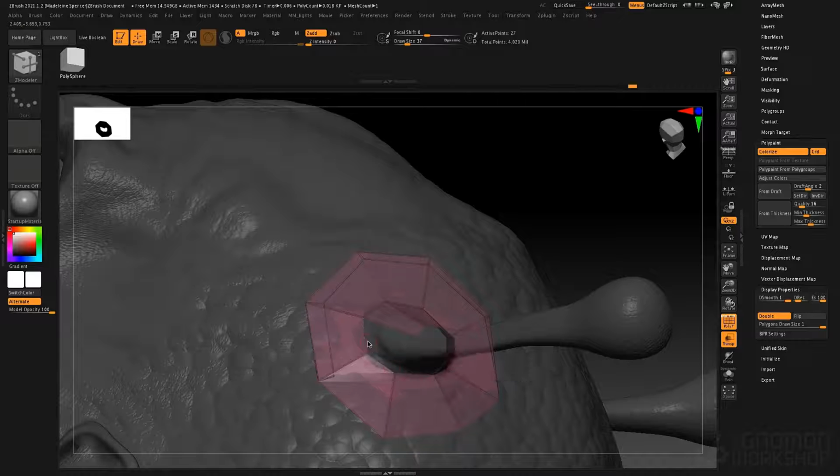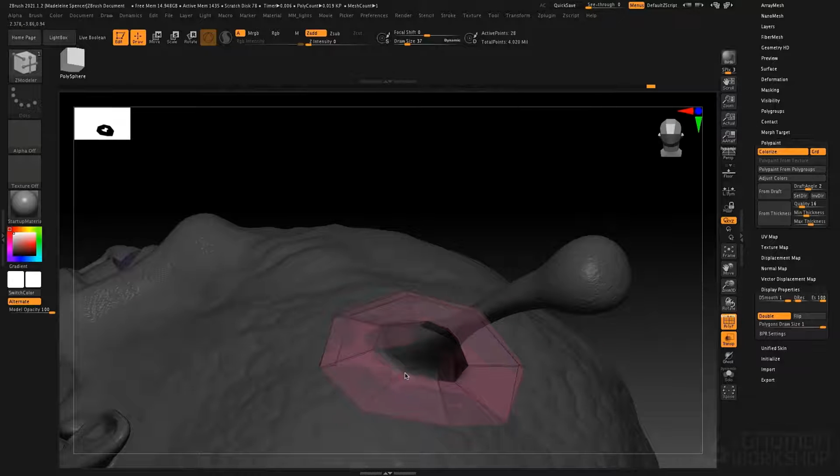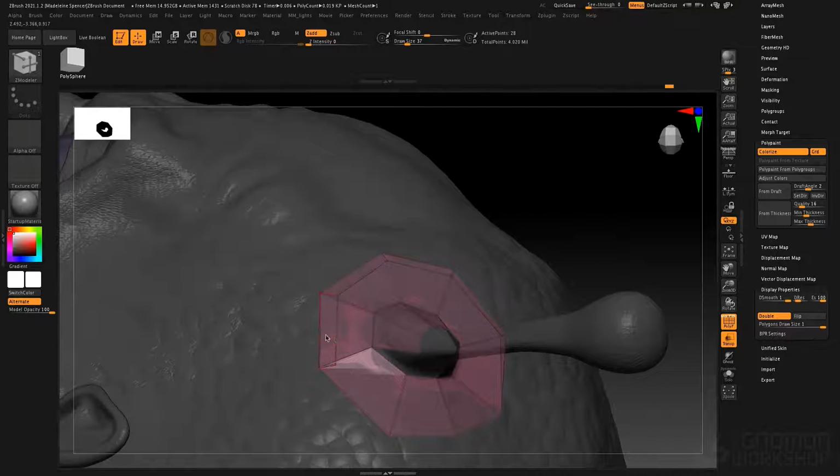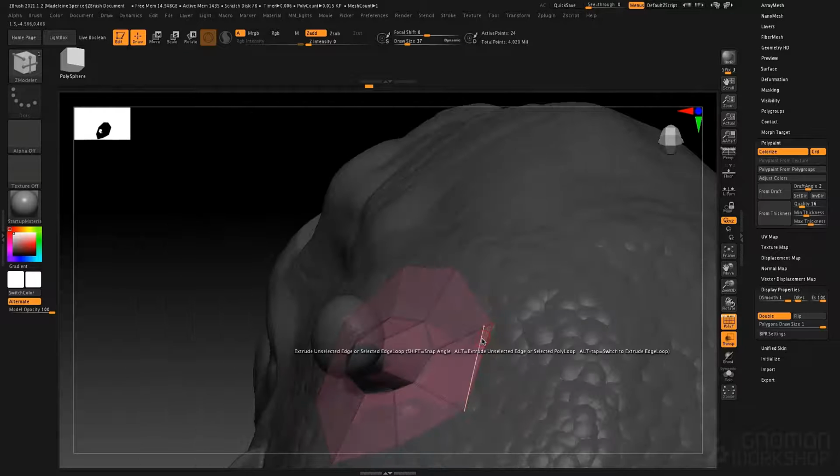And then we'll go back to our edge, bring this edge up to here, move this point, and let's move this point. So as we're adjusting these things, we can start to shift these faces around. Looks like we've got a little extra bit of geo right there. Let's get rid of that and that. You want to be careful about those little winged edges there.